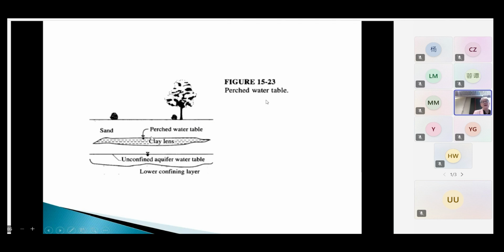But what can also happen is that you can have a water table kind of in the middle, and it's not a continuous water table. So you could get a little bit fooled when you go down, do your sample and think, hey, I've reached water, but maybe that's not the actual water table. And then you keep going down, and you'll find the actual water table, as you can see in this continuum. So the subsurface is a little bit confusing sometimes.